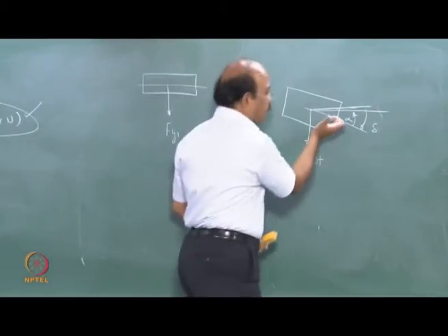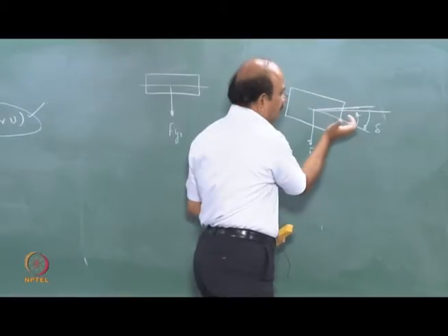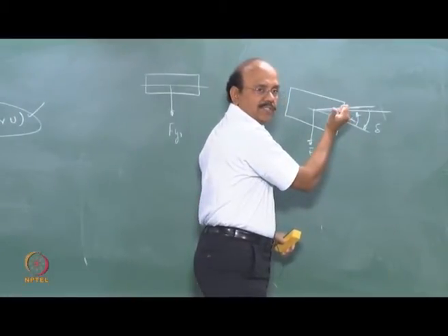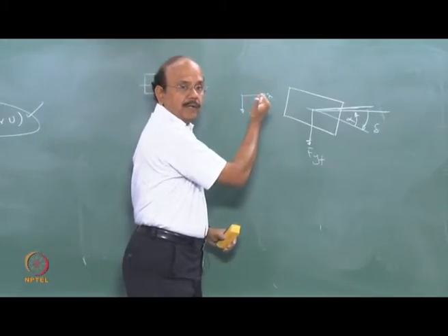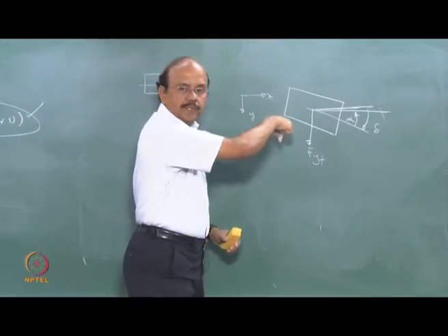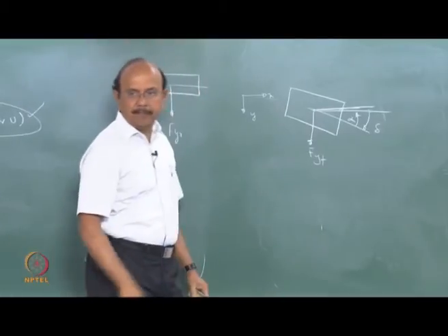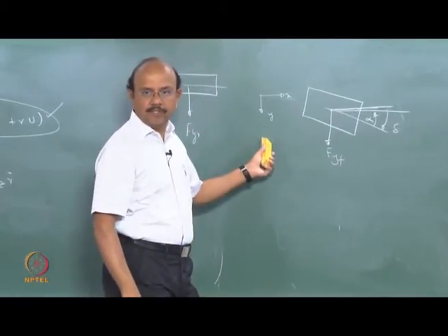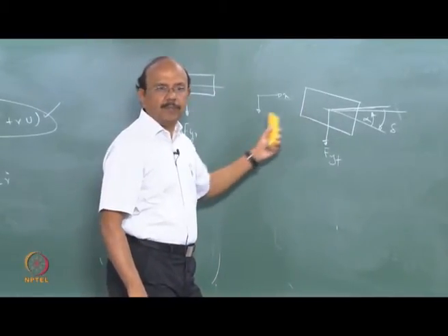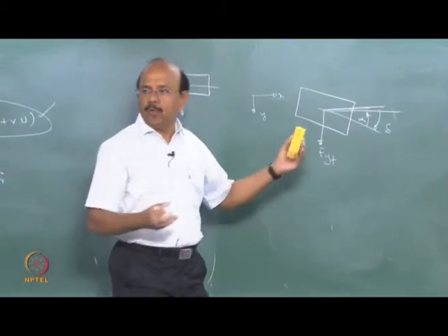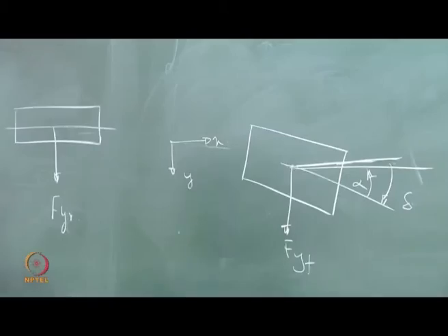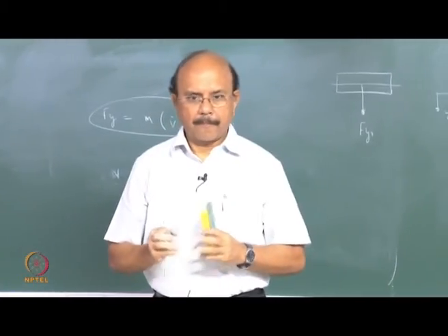The slip angle, look at that, is in this direction, which is in the negative direction, okay? And the force is created in the positive direction of y. So though we know this physically, we know how Fy is created, we have to be careful with these negative and positive directions when we write down the equations, right?